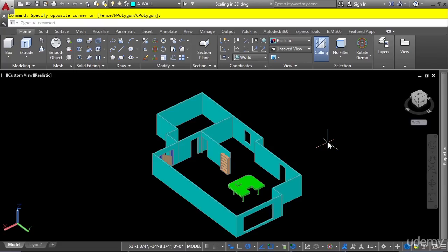With the 3D Scale gizmo, you can resize selected objects uniformly, resize them along an X, Y, or Z axis, or resize them along a specified plane. To specify the scale limitations, hover the cursor over the gizmo, highlight the solid area between the axes for uniform sizing, or highlight the double lines between the axes to specify resizing along a plane. You can also highlight an axis to specify resizing along the axis as well.